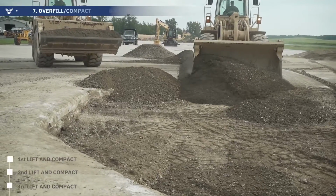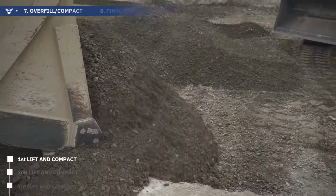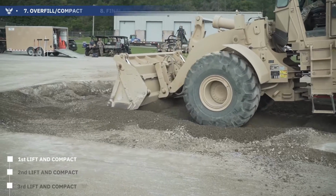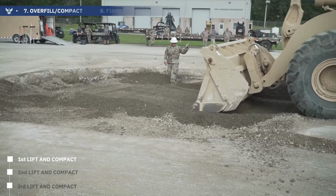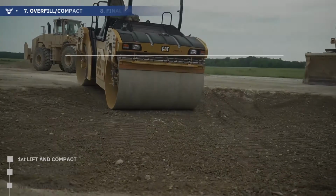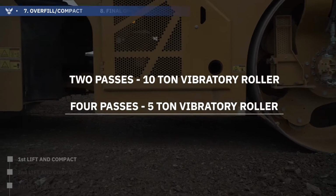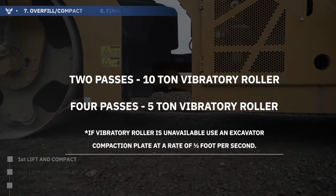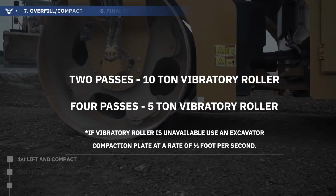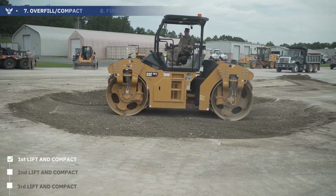Step 7. Overfill and compact crater. Place crushed stone material in the crater in lifts approximately 7 inches thick. Compact each lift of crushed stone using a minimum of 2 passes of a 10-ton vibratory roller, 4 passes of a 5-ton vibratory roller. If a vibratory roller is not available, use an excavator compaction plate at a rate of 1/2 foot per second. Now let's look at the remaining lifts.